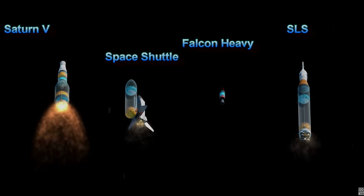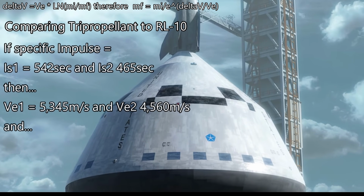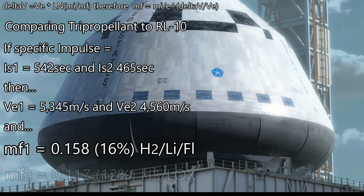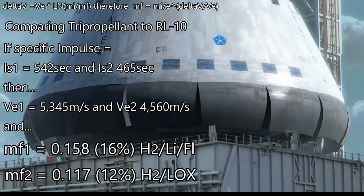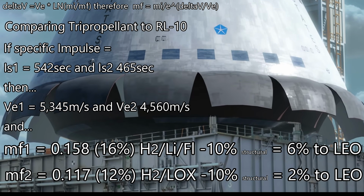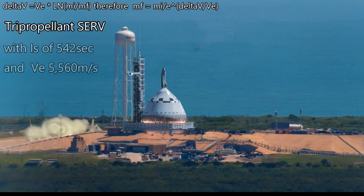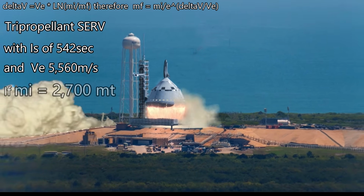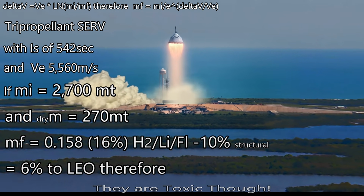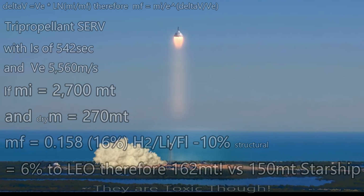But if we use this combination in a single stage-to-orbit rocket like the Chrysler SERV, and use fractions instead of actual mass, we see that we could get 16% of the launch mass into orbit, instead of only 12%. If we keep our dry mass at 10% of launch mass, we could triple our payload to orbit by using this system. That means a single stage-to-orbit ship like the Chrysler SERV, with a launch mass of 2,700 tons, keeping the dry mass to 270 tons, could get more mass to low Earth orbit than the two-stage Starship at its current rating. Is this the limit of chemical engine development?